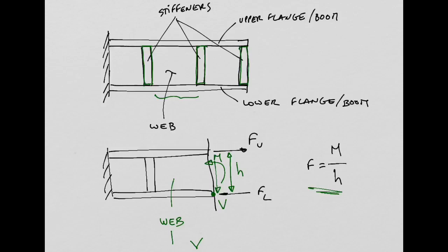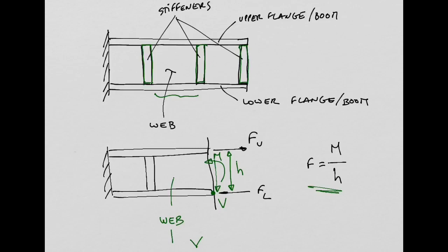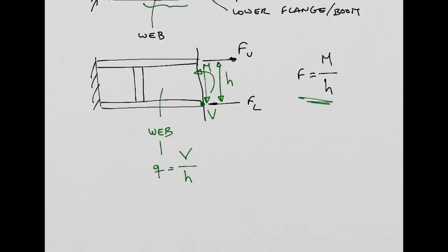And the thing is, as everything in aircraft, we always want to design a lightweight structure. So we want, for example, the thickness of these webs, this web, for example, we want the thickness to be as small as possible. Okay? But if this thickness becomes... so there are two different ways you can design these webs. One is what we call the thick web. Yeah, just a moment, let me just finish it. What we call thick web is that, okay, you have this shear flow.